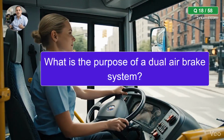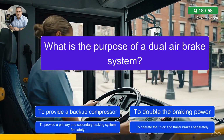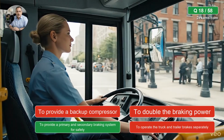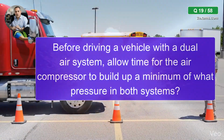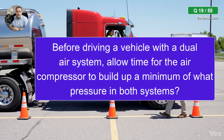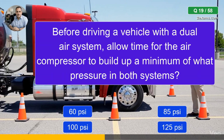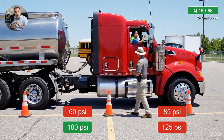What is the purpose of a dual air brake system? The correct answer is to provide a primary and secondary braking system for safety. Before driving a vehicle with a dual air system, allow time for the air compressor to build up a minimum of what pressure in both systems? The correct answer is 100 psi.